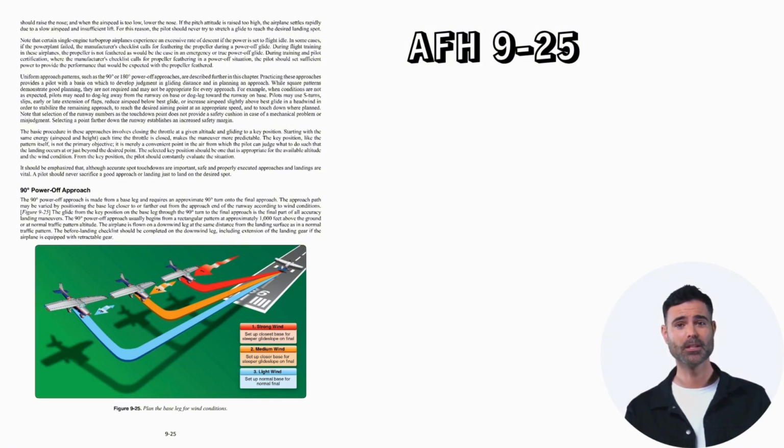Note that certain single-engine turboprop airplanes experience an excessive rate of descent if the power is set to flight idle. In some cases, if the power plant failed, the manufacturer's checklist calls for feathering the propeller during a power-off glide. During flight training in these airplanes, the propeller is not feathered, as would be the case in an emergency or true power-off glide. During training and pilot certification, where the manufacturer's checklist calls for propeller feathering in a power-off situation, the pilot should set sufficient power to provide the performance that would be expected with the propeller feathered.